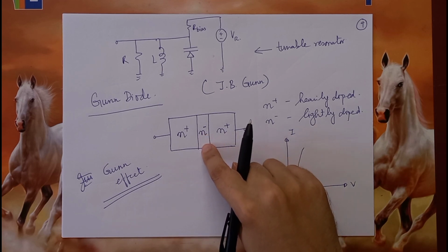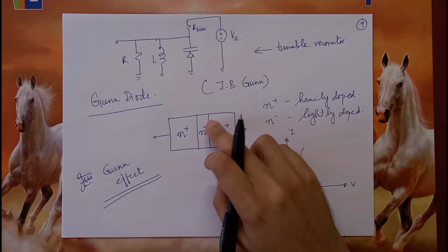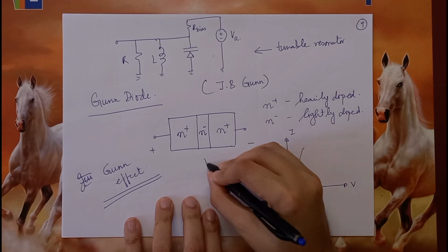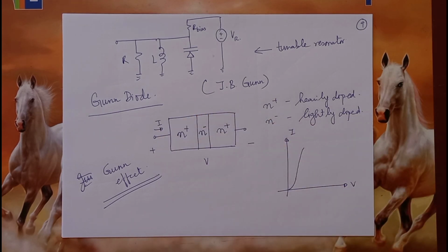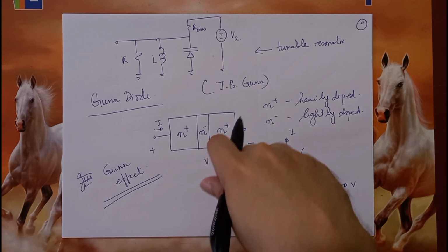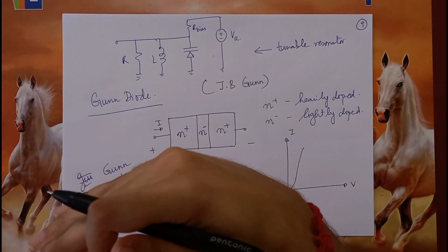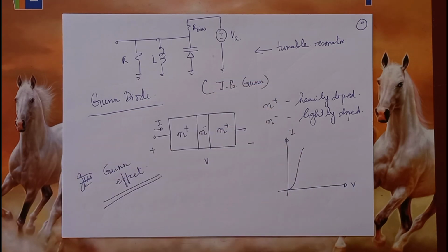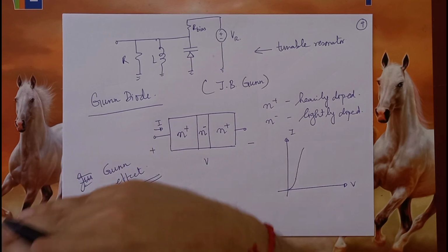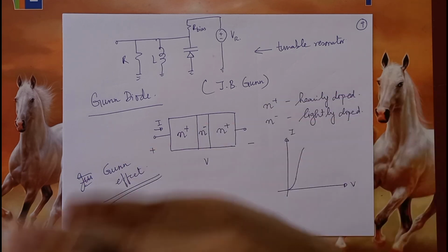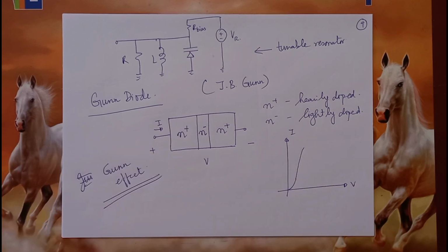But then, once the conduction is very high, if you start increasing the bias voltage across this, I call this V and this I, then the N- region starts playing a role. It causes the energy level of the electrons in the conduction band, which are already free, to increase. Therefore the effective start of the conduction band also increases.